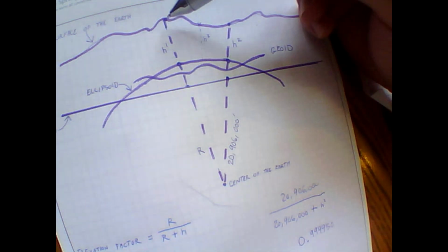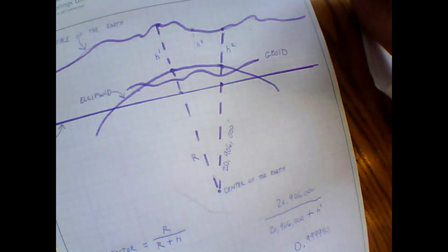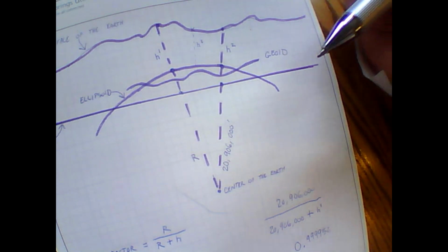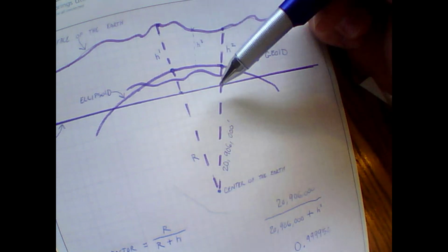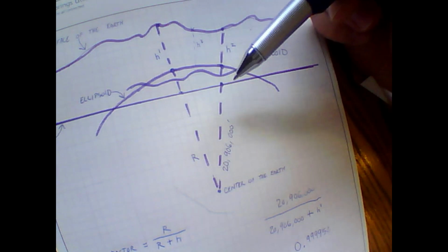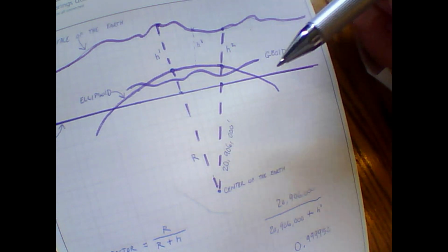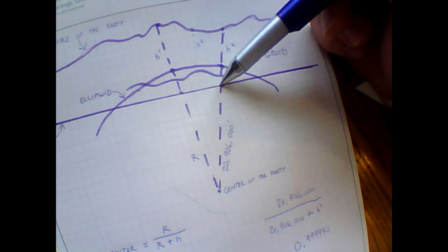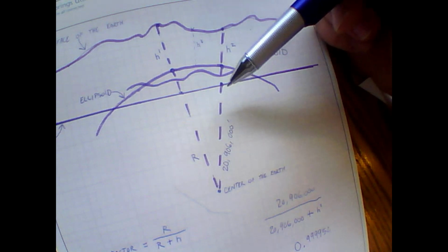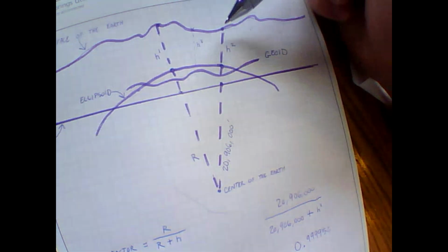So what you need to take into account is really just how this works and what's happening. The reason your distances are getting greater is because you're multiplying by the reciprocal, or the inverse, of your combined scale factor. Combined scale factor is going to be 0.99965. It's going to bring you down here. To get back up, it's going to be the inverse, 1.0035. Boom, your coordinates are changing by that, and you get up here.